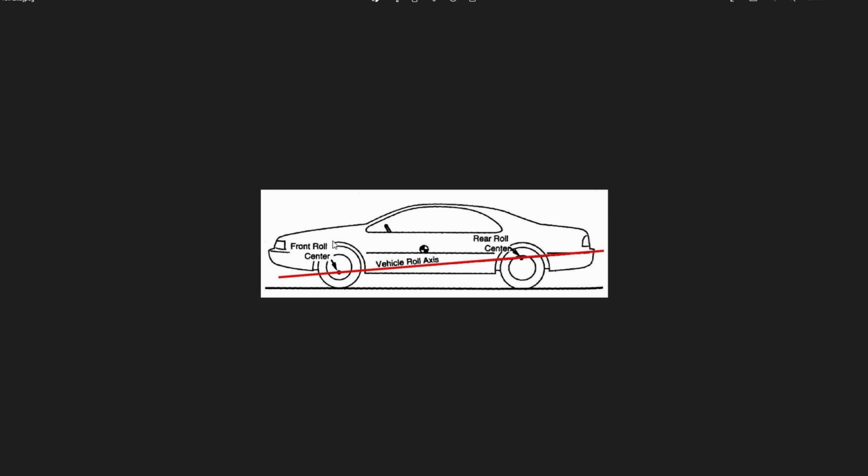If we think of it the opposite way, so the front roll center would be high and the rear roll center would be low. This is what, for example, plagued the HB back in the day. Maybe now less, but if you watched a lot of sort of hobby drivers, they would have a car that they accelerate and the rear is fishtailing a lot. Well, we can explain it through this also. So high front roll center, high geometric roll resistance. The car is quite responsive. The front end bites quickly, turns the car into the corner.